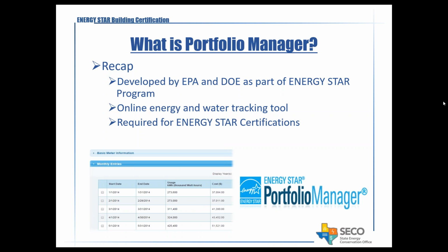So what is an Energy Star Portfolio Manager? It was developed by EPA and DOE as part of the Energy Star program. It's an online energy and water tracking tool, and it is a must for Energy Star certification. In other words, if you want to certify your buildings for Energy Star, you must have the data entered into the Energy Star Portfolio Manager, and it generates certain documents as a result of that. As a requirement, Energy Star Portfolio Manager is a must, basically. So that's important to keep in mind.